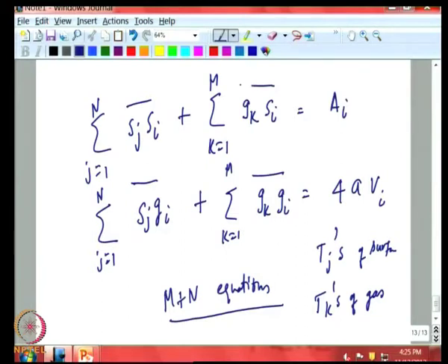So, the final accuracy of all this calculation is not sensitive to what technique you use here, but is much more sensitive to the accuracy of the input data. So, today in order to get a more accurate estimate of furnace efficiency, we need more accurate data input, and that is why the real challenge is not in the analysis part, that is all very well developed and settled, but it is much more sensitive to the kind of input data.